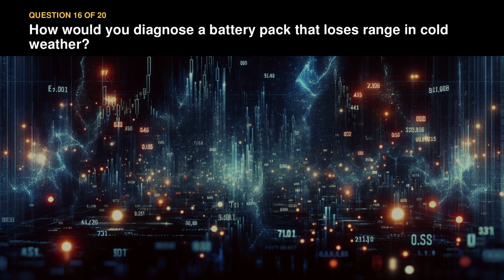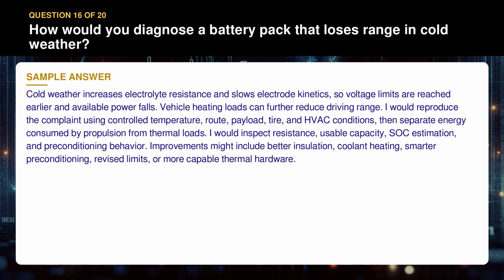Question 16. How would you diagnose a battery pack that loses range in cold weather? Cold weather increases electrolyte resistance and slows electrode kinetics, so voltage limits are reached earlier and available power falls. Vehicle heating loads can further reduce driving range.